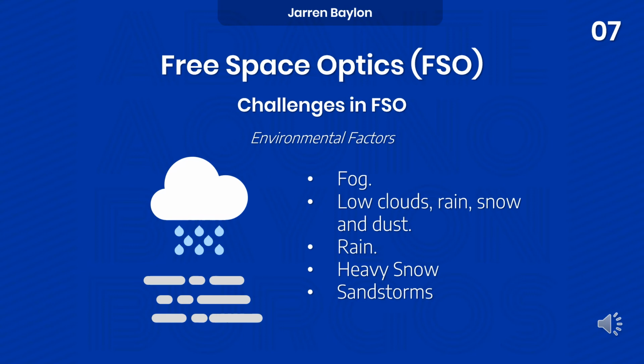Next is the low clouds, rain, snow, and dust. Low clouds are very similar to fog and may accompany rain and snow that may significantly degrade optical signals. Next is the rain. The rain can also degrade the performance of an FSO transmission. Raindrop sizes are larger than fog, so this may cause scattering of optical signals as well. Extremely heavy rain can entirely disrupt the link. Water sheeting on windows can also deteriorate the signal.